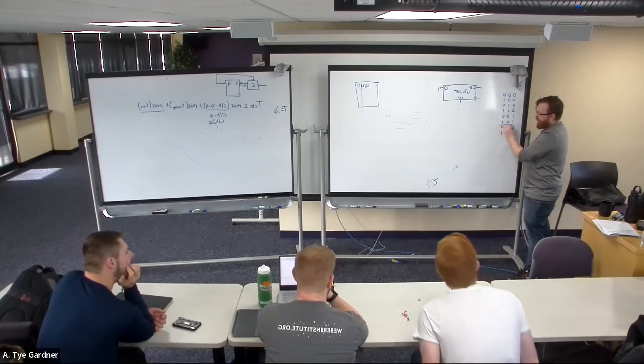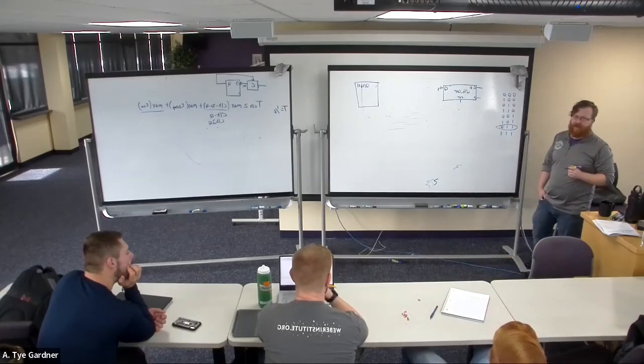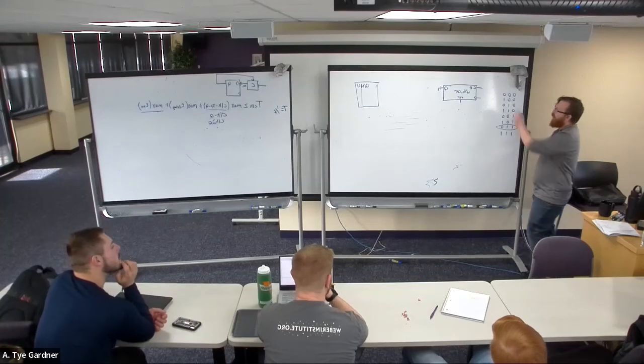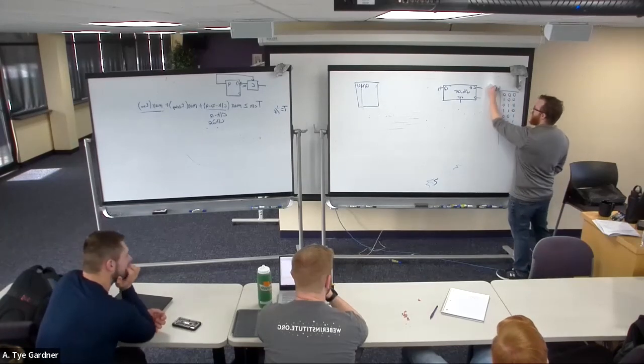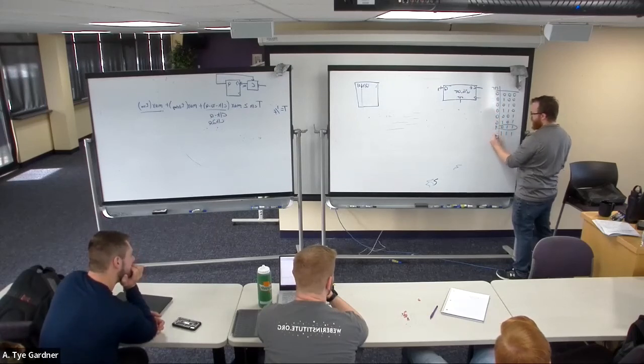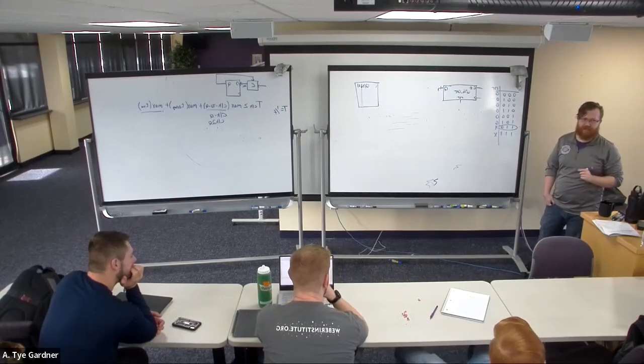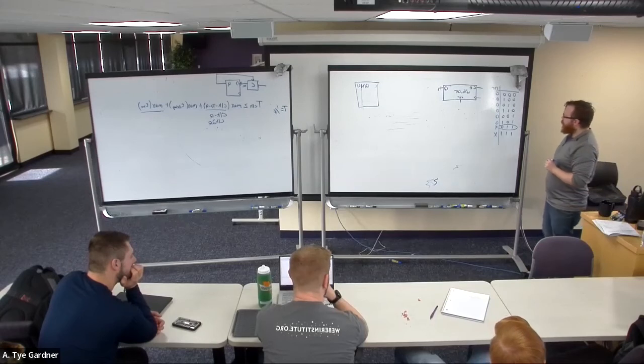Well, that means this is a good reset, right? And we could actually do this with the K-map, saying this is reset and don't reset, don't reset, don't reset, don't reset, don't reset, don't reset, do reset, don't care. Right? I should never see that.